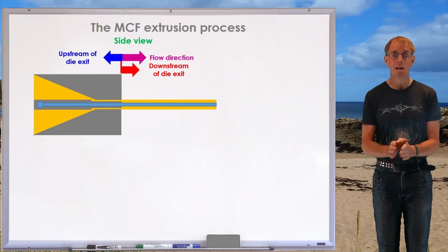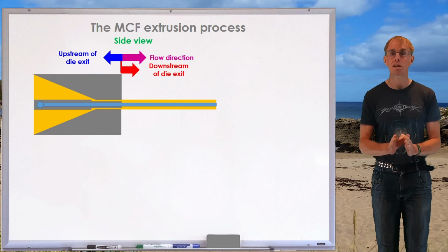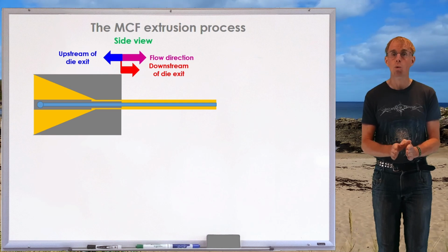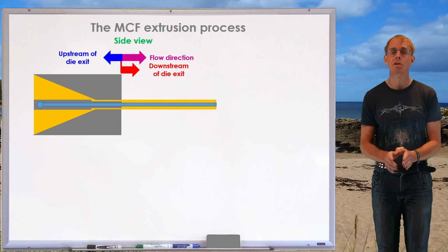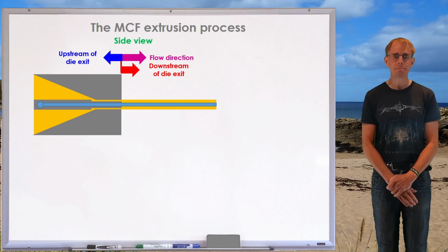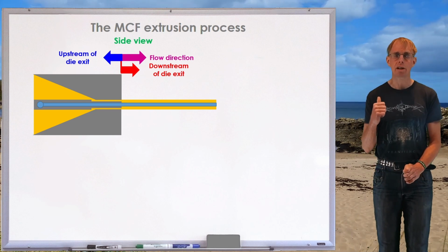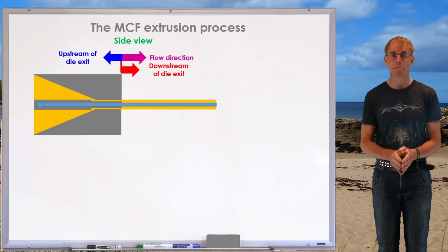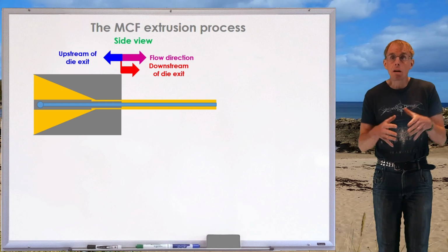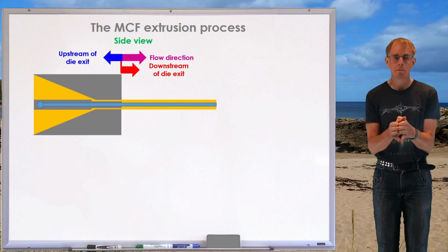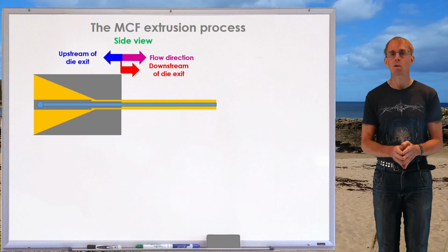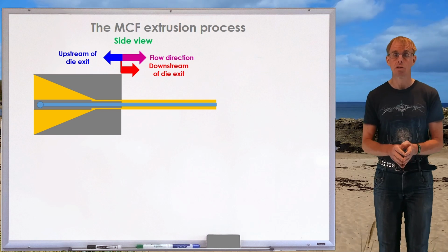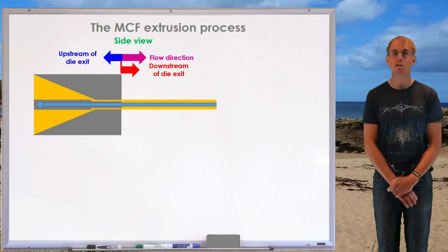That planar product is a film somewhere between 15 and 20 millimeters wide when it's undrawn, and when it's drawn down, somewhere between 5 and 6 millimeters wide. Now, placed within the extrusion die is an injection head. That injection head is streamlined to fit within the extrusion die and consists of effectively an air conduit. So the outer part of this injection head is connected to atmosphere.